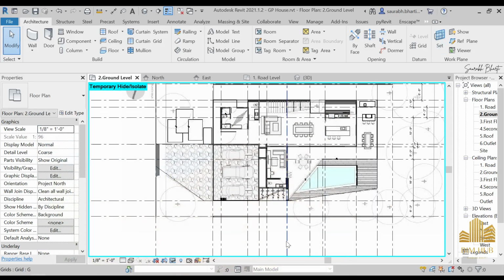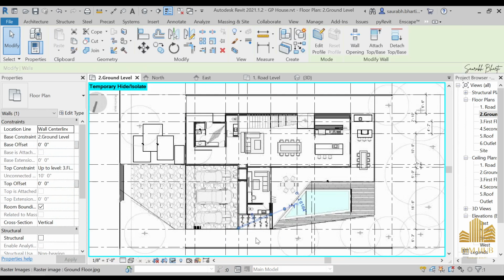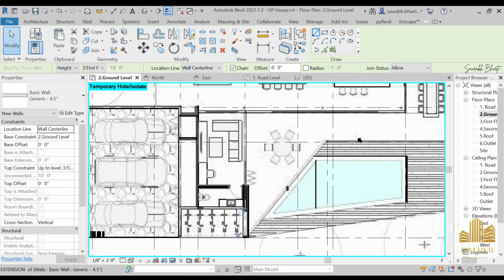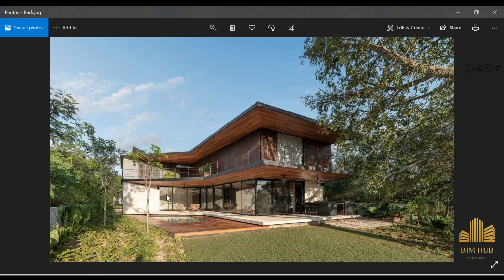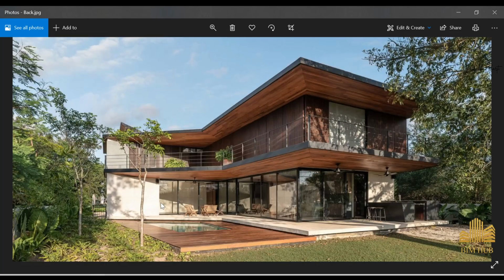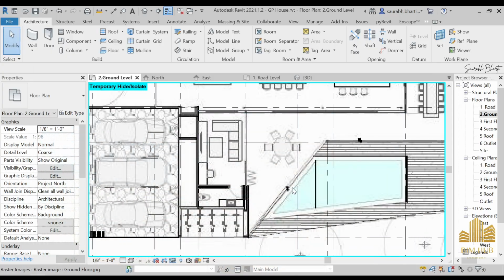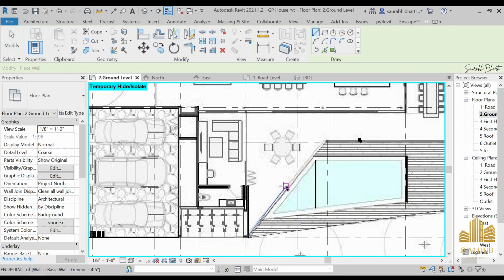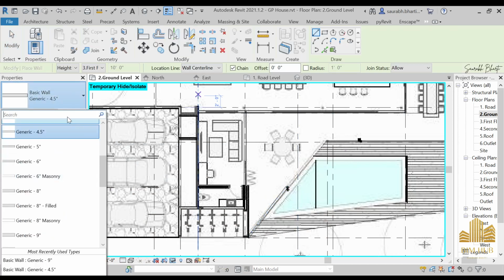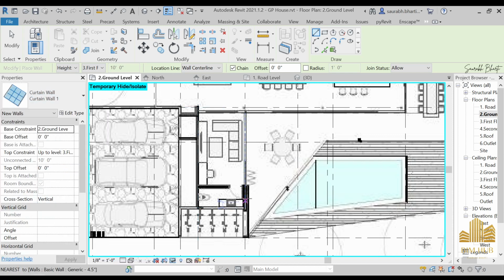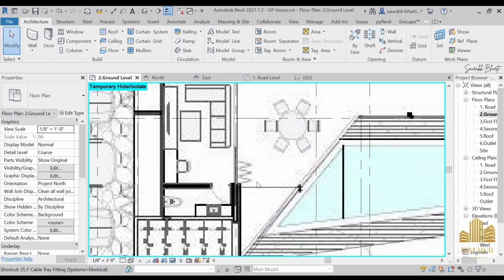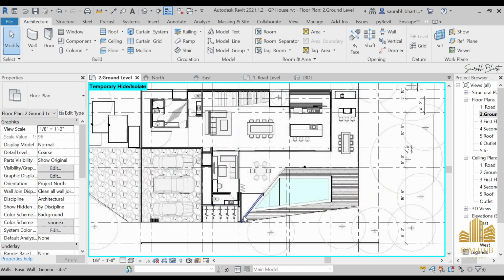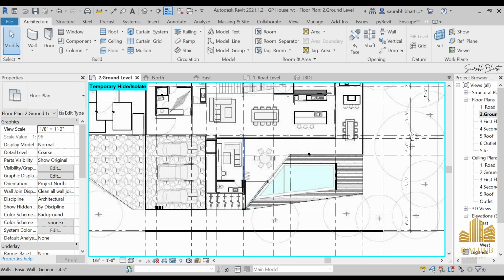So okay, what we are going to do is delete this one. No, this is not here. Just go to wall and select your wall from here to this place, and this is a wall over here, and after this place this is on the inner side, and from here we can make a wall. So just take WA, and here you can select your curtain wall. So just take a curtain wall, and from this wall just make something like this, and then trim it out from here to here, and now we have a portion like this.